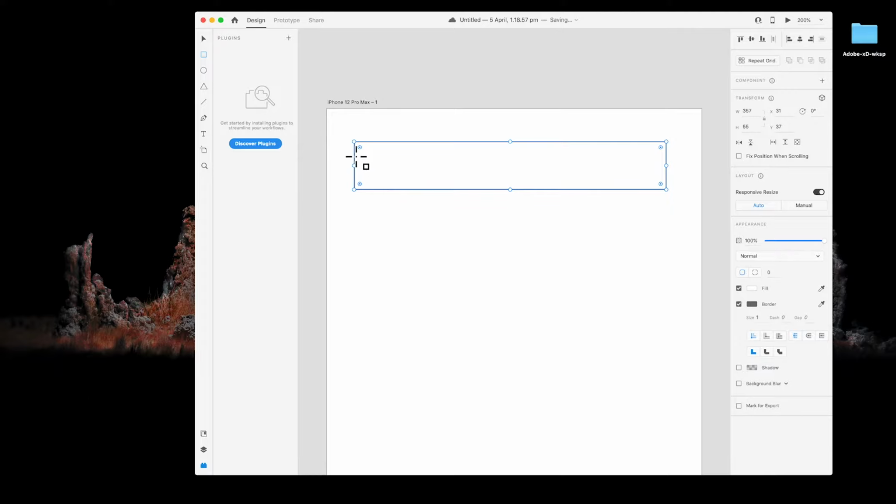These small circles allow you to resize the rectangle or change its dimensions. On the inner corner of the rectangle, you can see smaller circles in between the corners. You can select the circle over here and drag to change the corners of the rectangle into rounded corners.